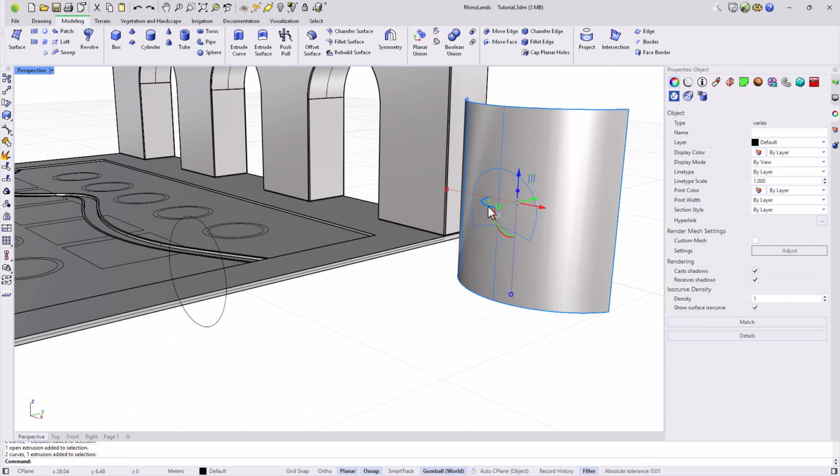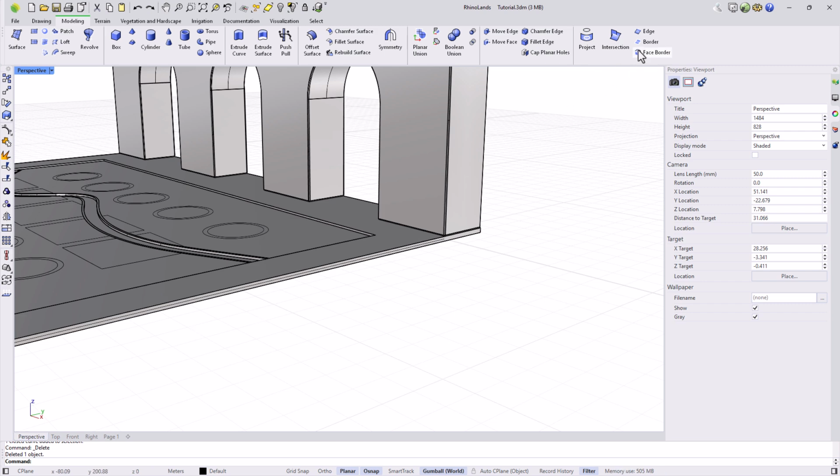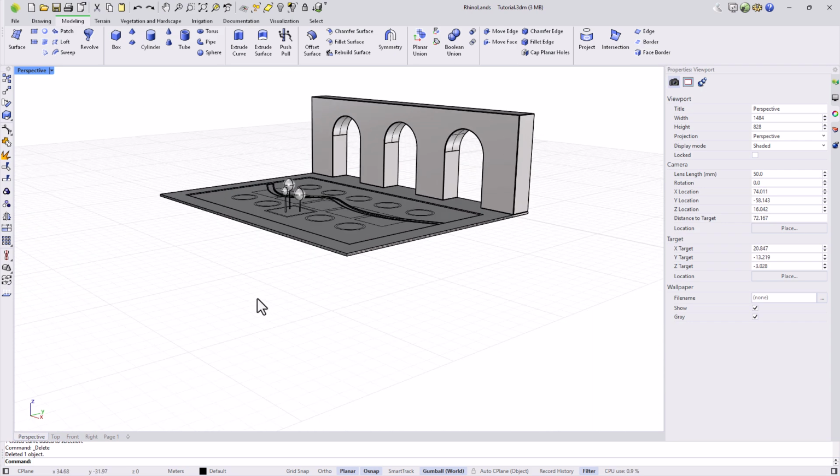With the rest of the operations, we extract curves from surfaces or solids. For example, we have options to duplicate a selected edge. Duplicate the edge on a surface or duplicate the edge of a face if it's a solid. With this, we finish the breakdown of the tools in the Modeling tab.